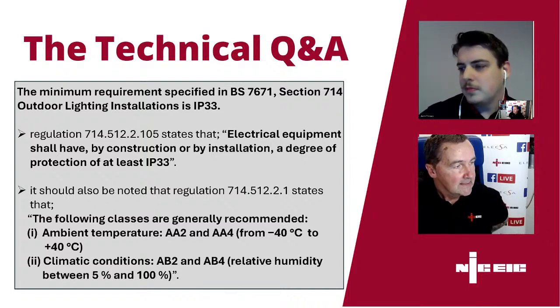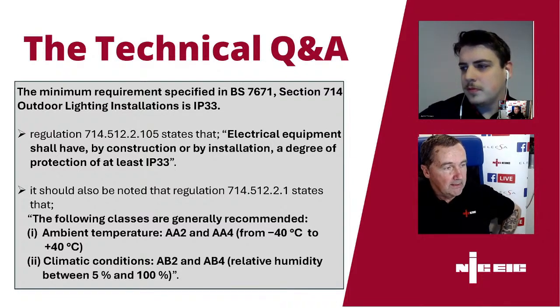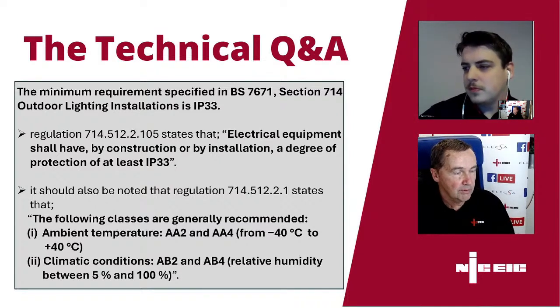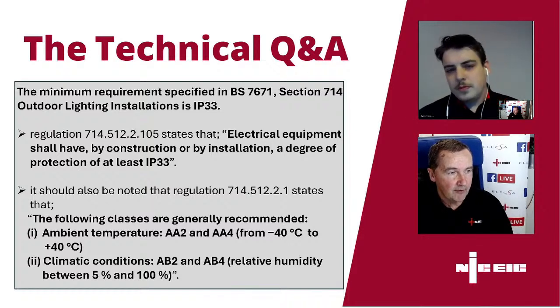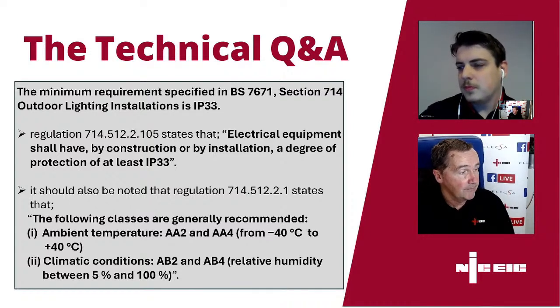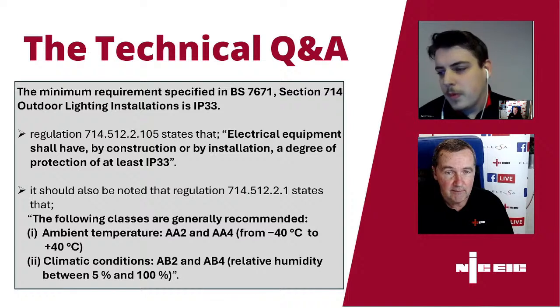What would you advise? Totally understand why. Although an RCD would give the maximum Zs you can probably achieve, you wouldn't want to put a single point of failure at the front end of a large installation like that. As one of the other engineers has referred to later in the chat, have a look at 419.3, which talks about when you can't achieve the maximum Zs for your protective device because, like in your instance, your Ze or your Zdb to the first board is already higher than the maximum Zs for your protective devices.